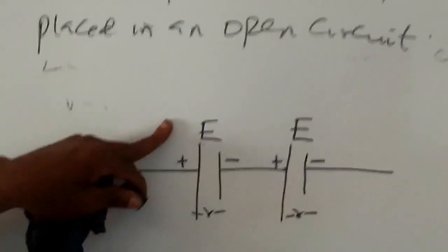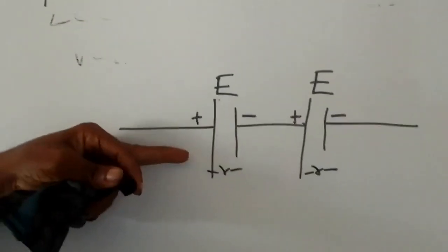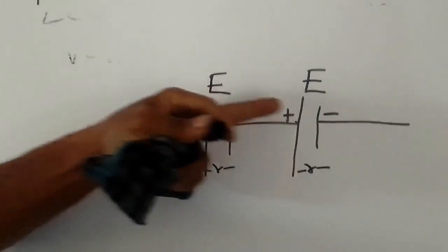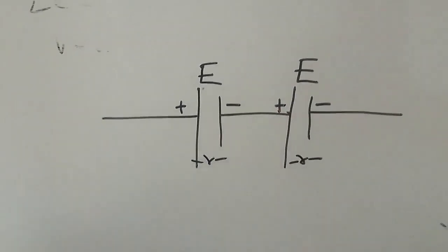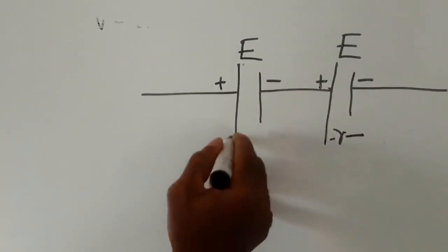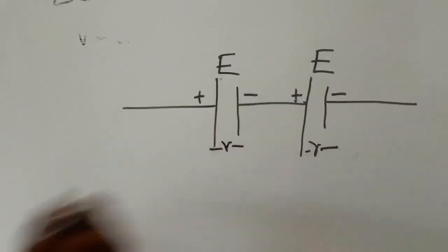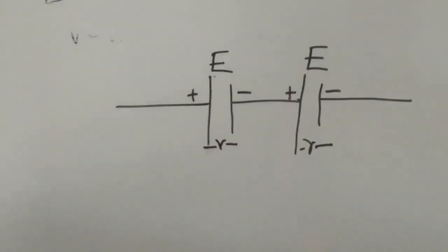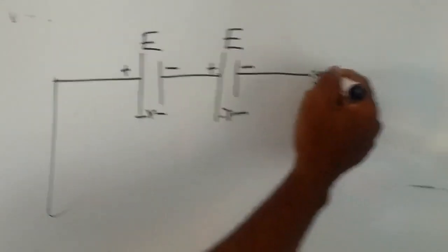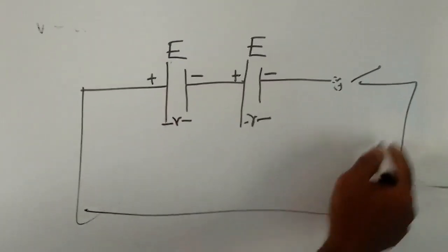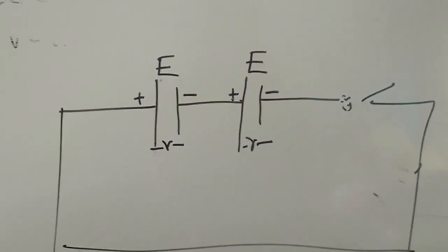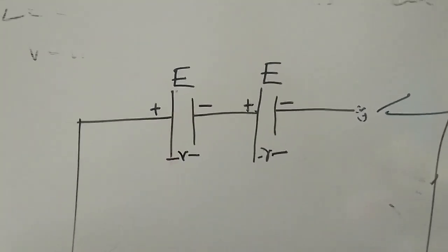Now the dry cell, or the one we use in our transistor radio, has an EMF of 1.5 volts. Two of it connected in series now give us 3 volts. While small letter r stands for internal resistance, which is the resistance offered by chemicals within the terminals of the cell. So that is the cell which provides electrical energy in a given circuit, and every cell, as we said, has an EMF, which is called electromotive force.